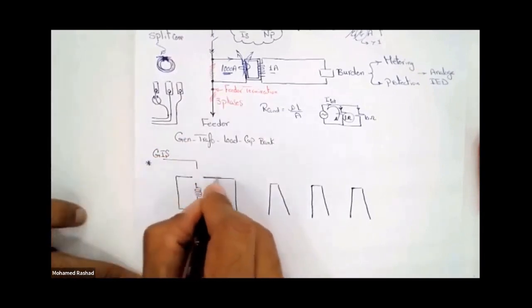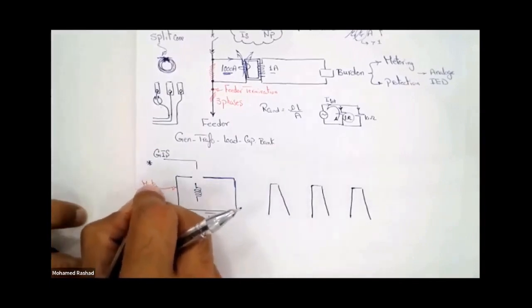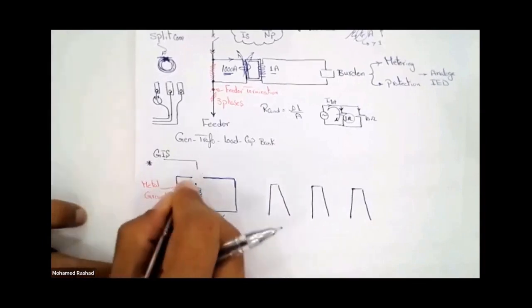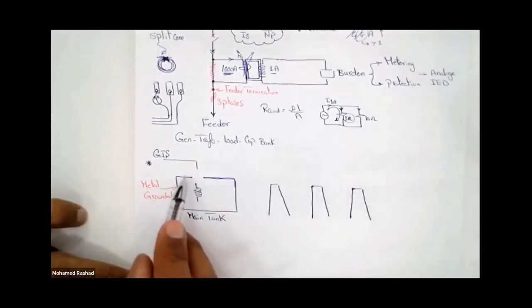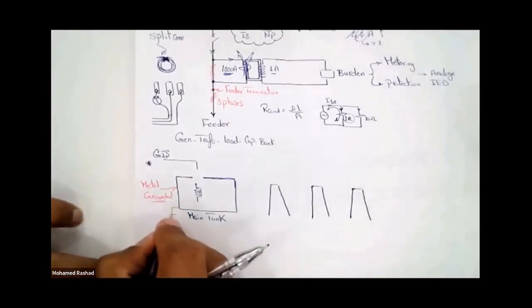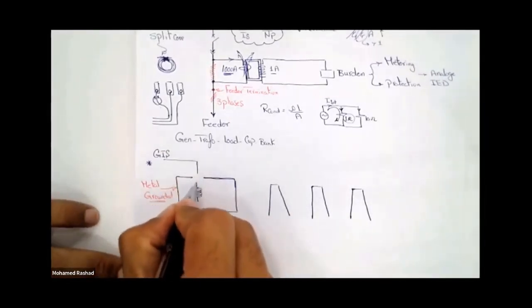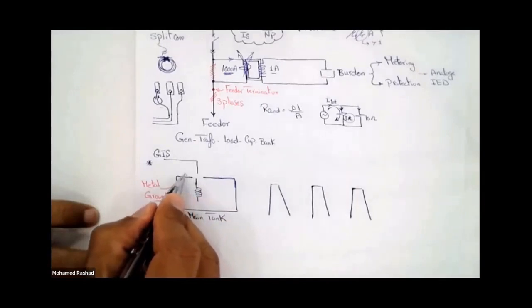Now the body of your transformer tank, it's metal, right? Metal. And at the same time, it's grounded. This part of the transformer is metal, and at the same time, it's a non-current-carrying part, meaning it's not supposed to carry any currents, right? And it's grounded. So of course, when you're entering with this conductor to get in here, surely around you is the tank body. So because of any moisture or dust, you must leave a distance between here and the tank body itself.